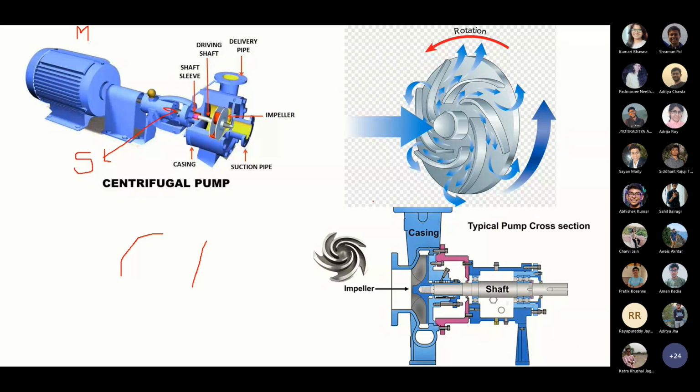So, as I just explained, in case of fan, when this impeller rotates, whether clockwise or counterclockwise, what will happen at the center point? Always there will be generation or the creation of vacuum pressure. Because of the centrifugal force, and centrifugal force acts in the same direction, once the fluid displaces outside, definitely there will be vacuum generation. The vacuum generation always happens at the center point.